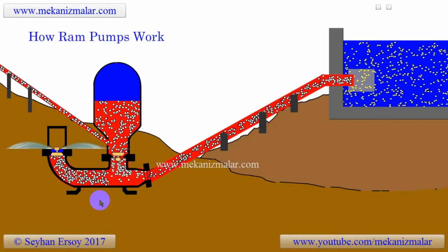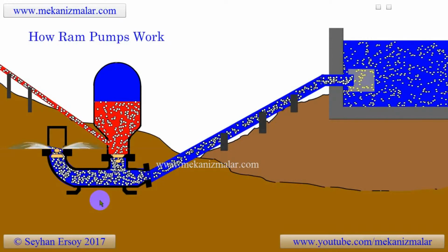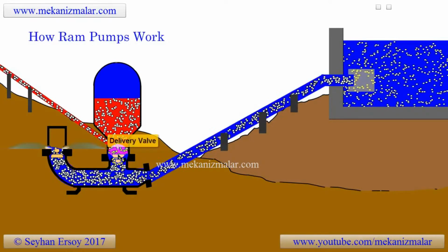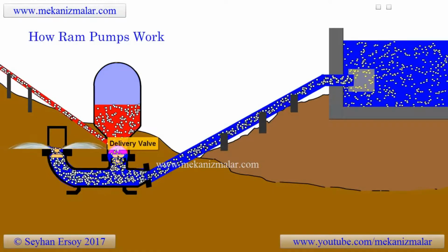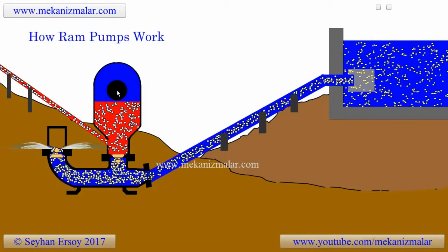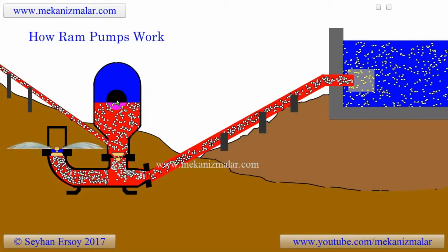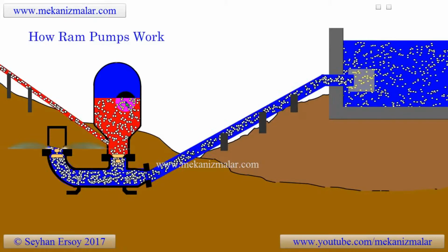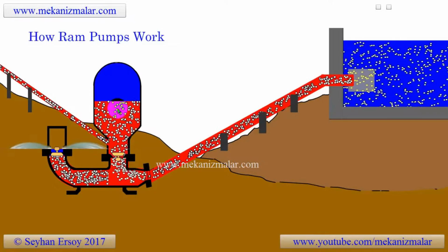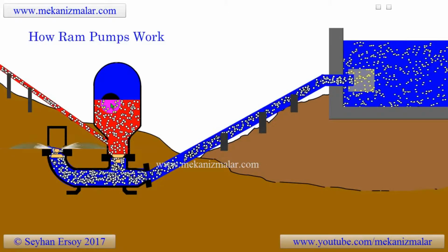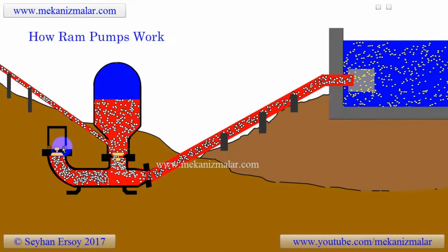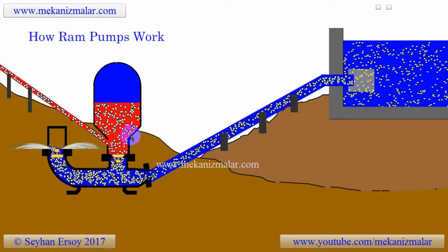Increased water pressure within the pipes must be relieved to prevent damage to the system, and this is done by the delivery valve. The high pressure in the inlet pipes opens the delivery valve, which directs the pressurized water to the accumulator compartment and the delivery pipe at the same time. While the water level is rising inside the accumulator, the air pressure trapped above increases. Sometime later, the water closest to the waste valve moves backward toward the accumulator, causing the waste valve to open, and the cycle repeats itself all over again.